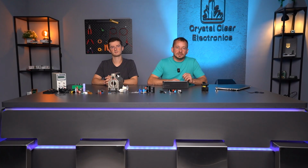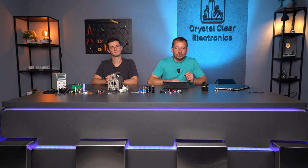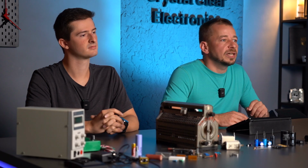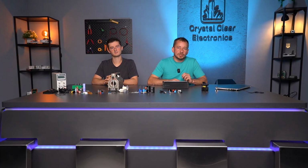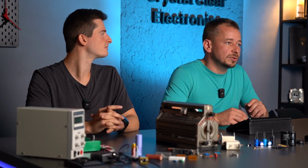You will experience this when you try it. If we force too much current through the resistor, then a lot of electrons will collide, and it may generate a huge amount of heat, which may cause the resistor to burn. Each resistor has a parameter which shows how much electrical power it can absorb without damage at a given ambient temperature. If it is exceeded, then the resistor can warm up so much that it will cause permanent damage in its